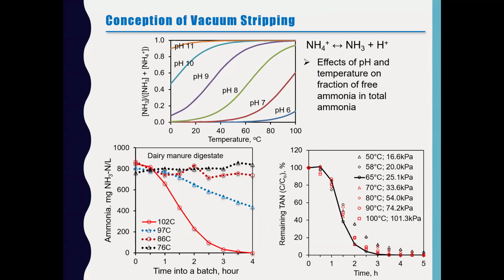To strip ammonia out, we first need to convert aqueous ammonium to ammonia gas, so the ammonia gas can transfer from water to air bubbles and be carried out. This conversion is achieved at increased pH and increased temperature. Mostly for air stripping, water pH is increased to above nine. And if heated, for example to 60 degrees Celsius, free ammonia gas accounts for more than 90% of total ammonia, ready for ammonia stripping.